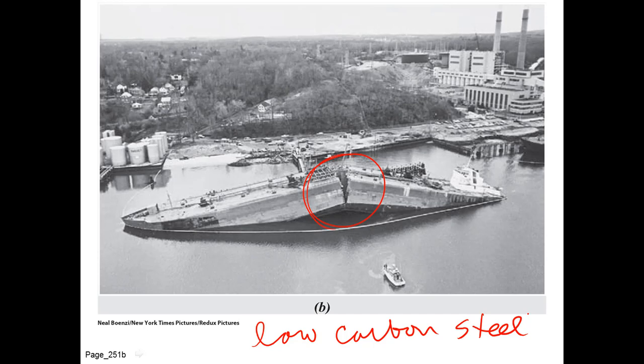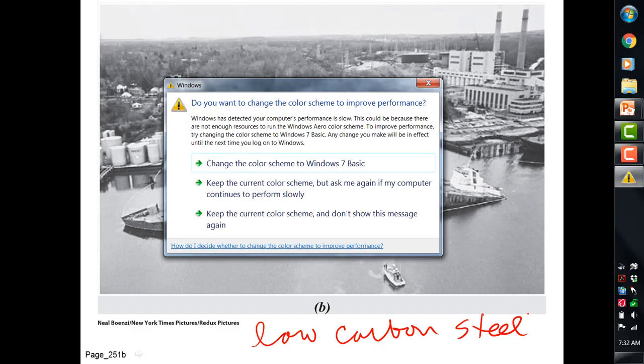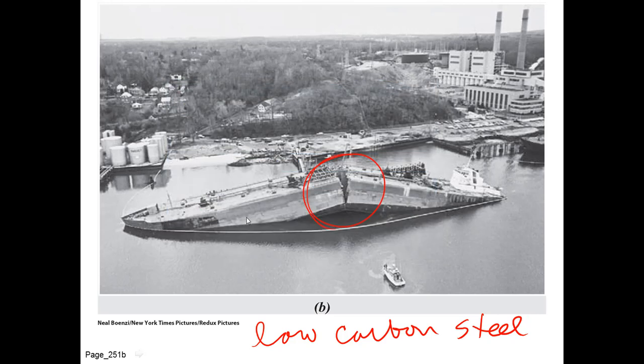And you can imagine if the ship set sail, say, from a warm water port, the steel might be in a ductile condition. Sorry about that. This ship sets sail from a warm water port. The girth is in a ductile condition, goes north and encounters very cold conditions. It becomes brittle, and the failure then ensues. So we'll look at that in great detail.